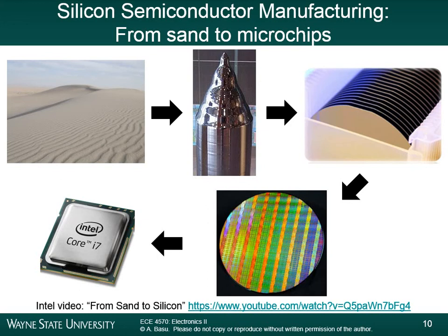But what happens is, we'll talk about this later when we get to the next module. Temperature actually slows down how fast carriers can move through the device. So when you bring down the temperature of a device, you're reducing something called lattice scattering. And so electrons can travel faster through the device, and that's why the microprocessor operates faster at cooler temperatures. However, that's only the tip of the iceberg. We'll talk a little bit more about that in the next chapter.